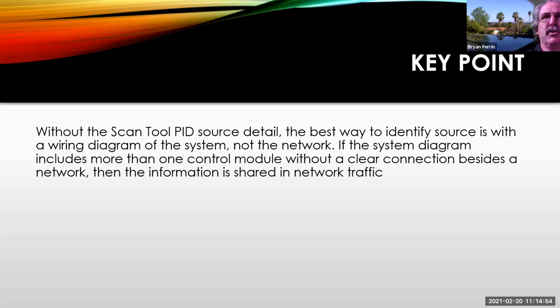Because many times, if a module might not convey information, it could be a sensor problem. Hey, I can't trust the sensor, so I can't share it. Or it could be something going on or a missing module. Therefore, the module that is supposed to be giving me that information isn't sending it. Therefore, for that PID, I'm going to give you a default value.